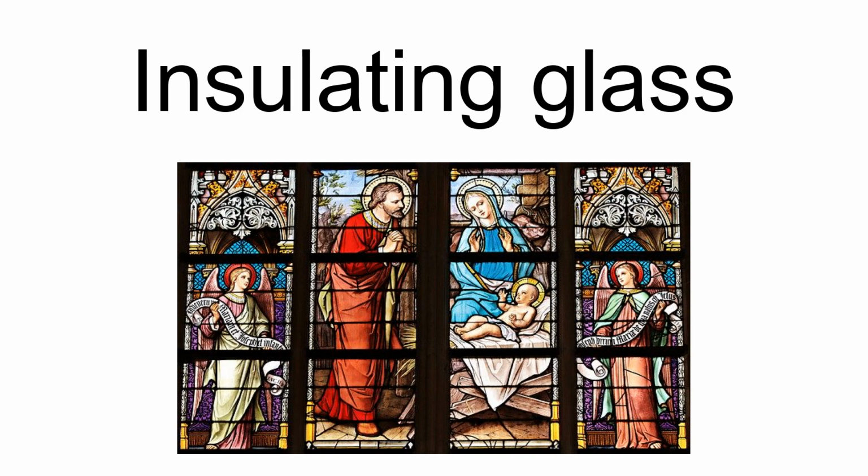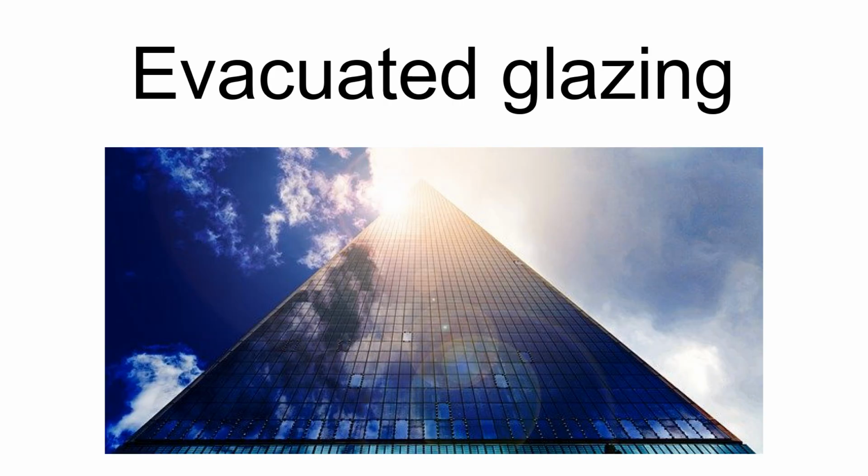buildings. A 1994 innovation for insulated glazing is evacuated glass, which as yet is produced commercially only in Japan and China. The extreme thinness of evacuated glazing offers many new architectural possibilities, particularly in building conservation and historicist architecture, where evacuated glazing can replace traditional single glazing, which is much less energy efficient.